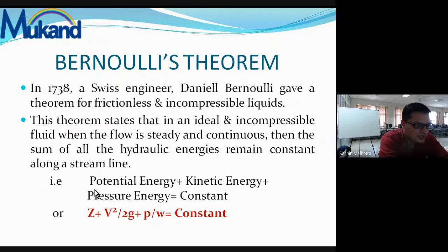So what this theorem is saying is that the sum of all the hydraulic energies remains constant, meaning the sum of potential energy, kinetic energy and pressure energy is equal to a constant. Or mathematically we can write: the potential energy is denoted by Z, plus kinetic energy is V square upon 2g, plus pressure energy is P upon small w. It is constant.